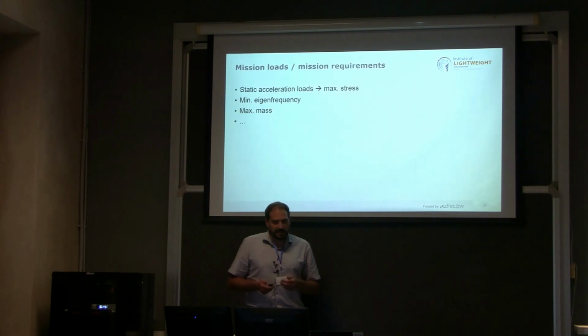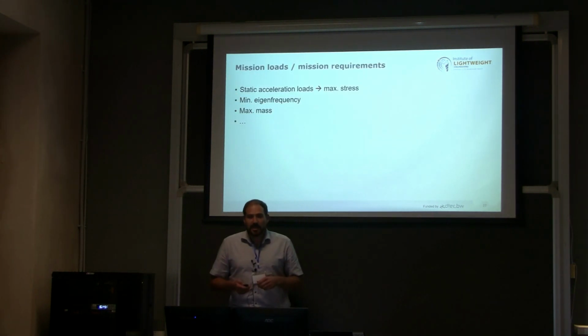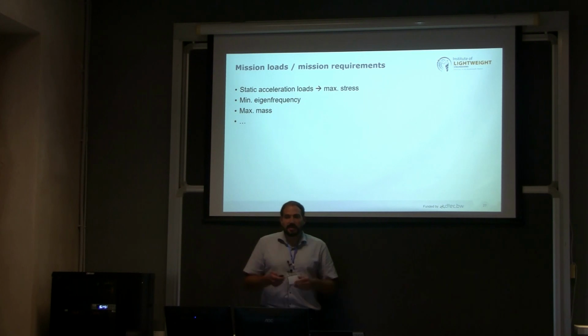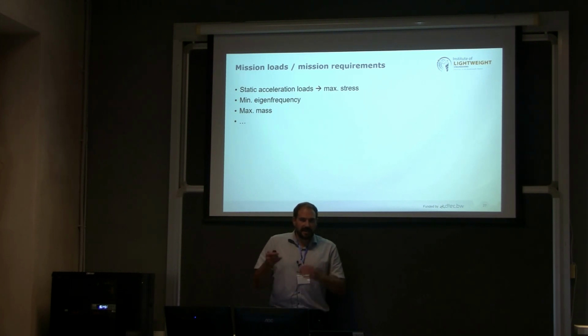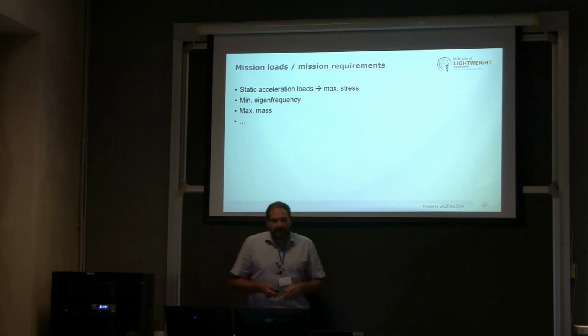These are the mission loads. For example, you have the static acceleration of the launcher, or you have to have a minimum eigenfrequency, a minimum stiffness, and maximum mass on the satellite. And there are other mission requirements. For example, you have to use exactly these screws or these supports, and so on.